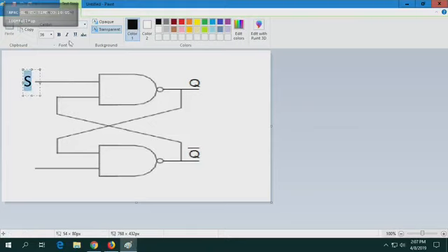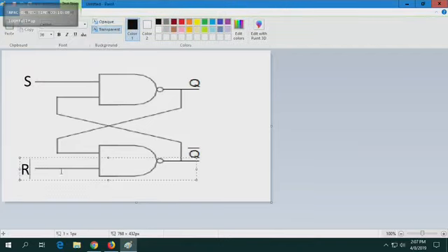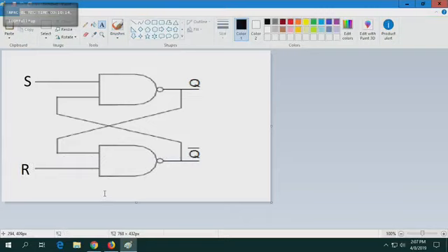Okay, we've got to do this the old school way. Usually I don't like writing notes in class, but some things you've got to do step by step. Can you draw that circuit? Can you see there's an S and an R, and those are two NAND gates. Everyone done? Simple system. Can you see how the output is fed back? Next, can you do the truth table for a simple two-input NAND gate?